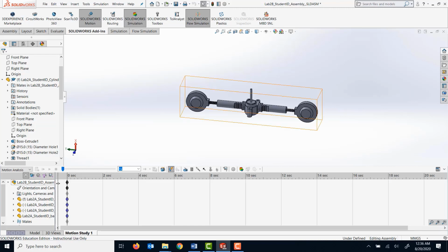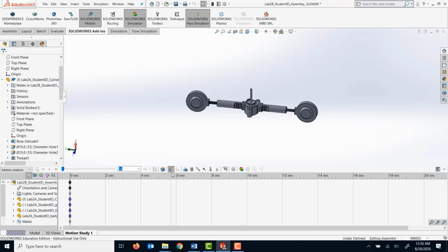With the motion analysis, you can do two types of analysis. You could do kinematics analysis, you could do the dynamic. With the kinematic analysis, you're basically solving for equation of motion, where no dynamic forces are involved, or there are no torques, the parameters are not calculated. With the basic kinematic analysis, you're just basically solving it for displacement, velocity, and acceleration, and so on and so forth.